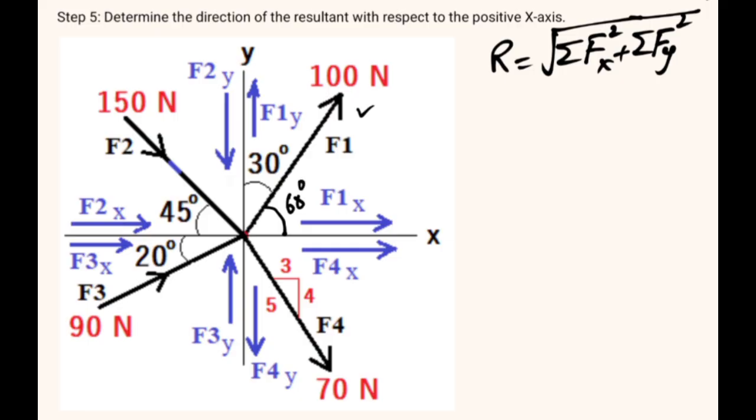So once you know the angle of this 100 Newton force with x-axis, you can find its component in x direction and y direction very easily, and you can say that F1x will be just equal to 100 cos 60, right? We take the cosine of the angle which it makes with x-axis, and that is 100 cos 60, and in y direction F1y will be 100 sin 60.